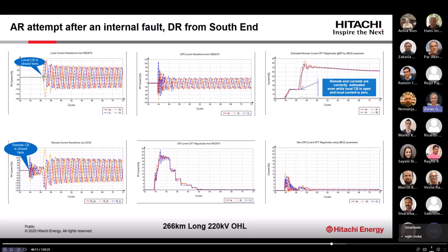But you can see the model-based one here. It can recognize even though the site where I do measurement doesn't really have the breaker closed, I get voltages and I can estimate exactly what needs to be on the other side. In the beginning, while the breaker is closing, I get maybe 6-7% of diff, but then it falls below 2% and keeps there, irrespective that you have energized the line and get the power flow and everything. It seems to be extremely exact.